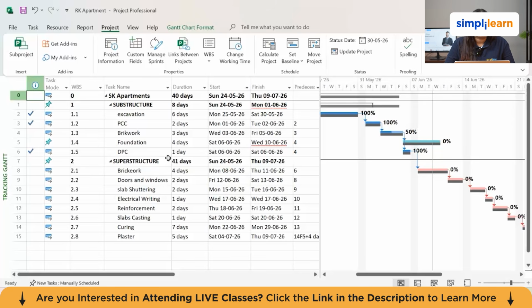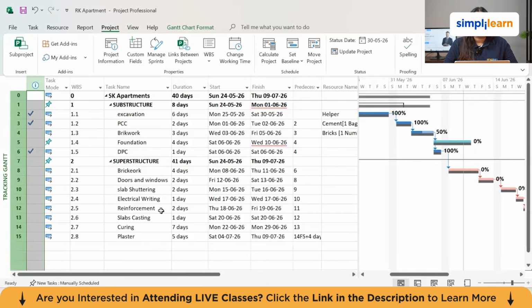Project managers who keep resetting their baseline to hide delays are not managing their project. They are hiding it. With the baseline set, we can now start updating the schedule with what is actually happening on site. MS Project will immediately show us where we stand against the approved plan. Progress tracking is what transforms your schedule from a plan into a management tool.